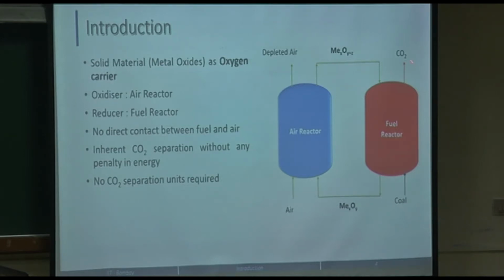To clean this gas or produce a concentrated stream of CO2, a lot of energy penalty and cost goes into the CO2 capture. Here you are readily getting a pure stream of carbon dioxide, which can be used for transportation and then storage. So this is an advantage which CLC has got.